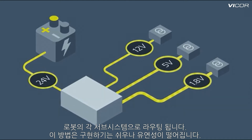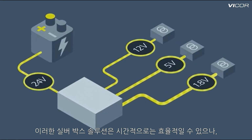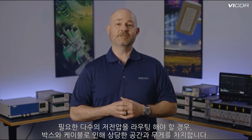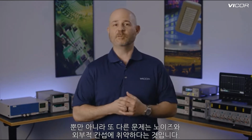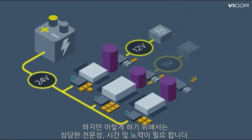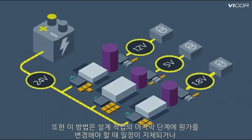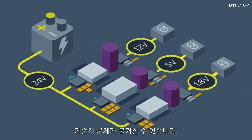It's also easy to implement, but it's not flexible, and we typically call it a silver box solution. While the selection of the box may be efficient for your time, having to route all those different low voltages can consume space and weight of the box and the cables, which also makes it susceptible to noise and external interference. Another option is to build the entire power supply yourself using discrete power components, but that requires considerable expertise, time, and effort. Now, if you have those, that's great, but if you need to change something at the end of the design process, it can be disruptive and risky to your schedule and the technical requirements.